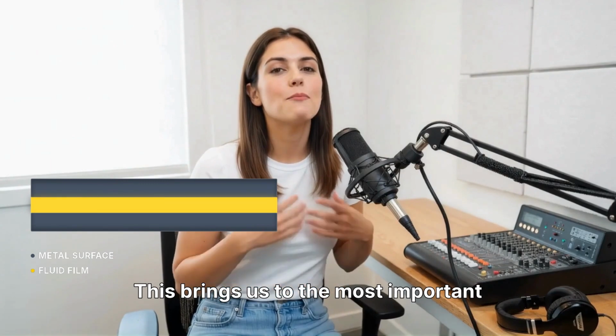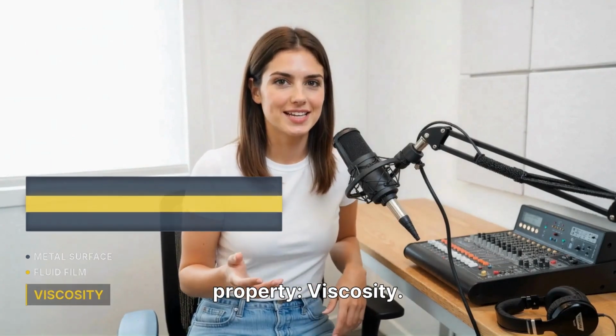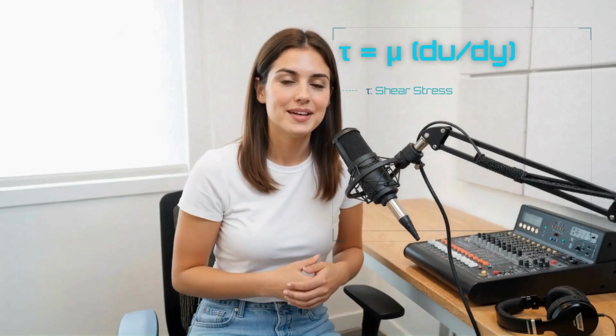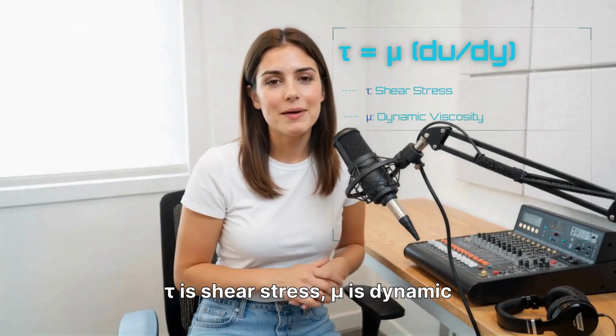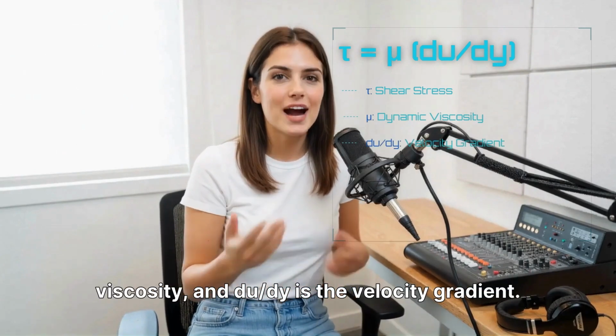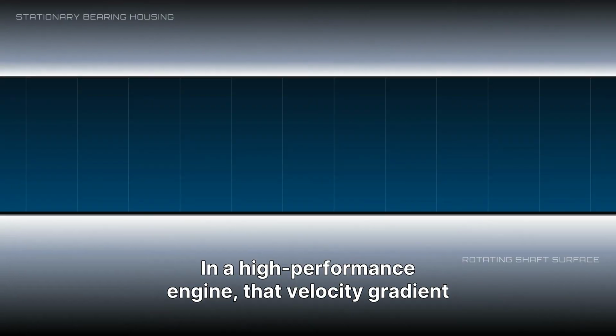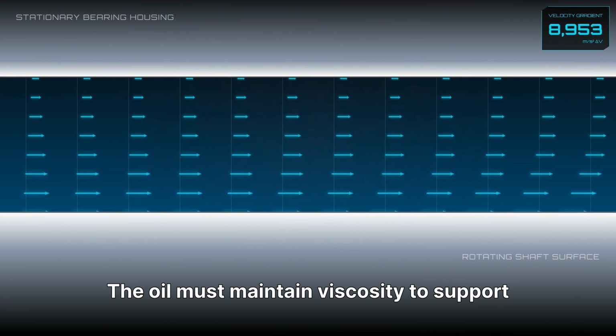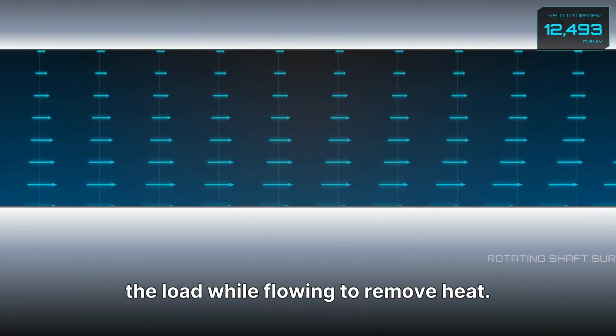This brings us to the most important property, viscosity. In fluid dynamics, this is governed by Newton's law of viscosity. Tau is shear stress, mu is dynamic viscosity, and du/dy is the velocity gradient. In a high-performance engine, that velocity gradient is massive. The oil must maintain viscosity to support the load while flowing to remove heat.